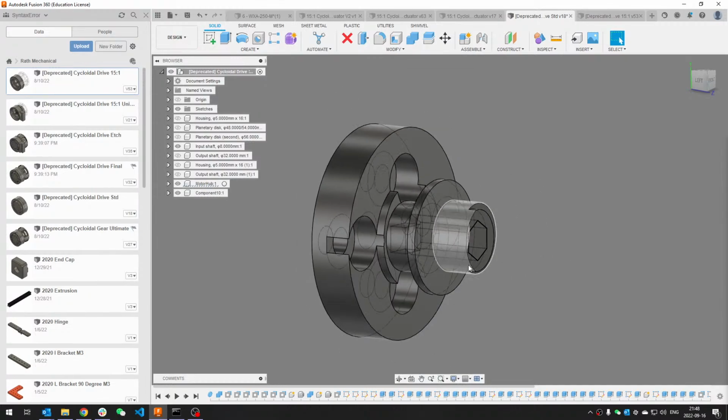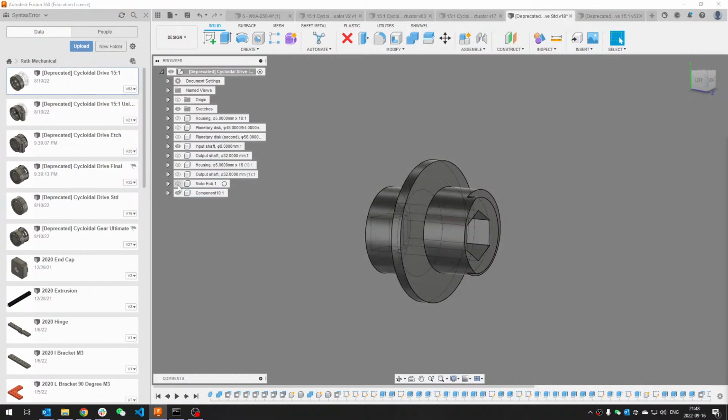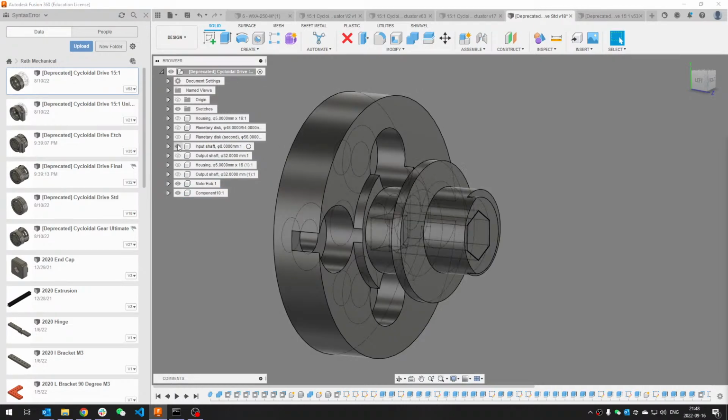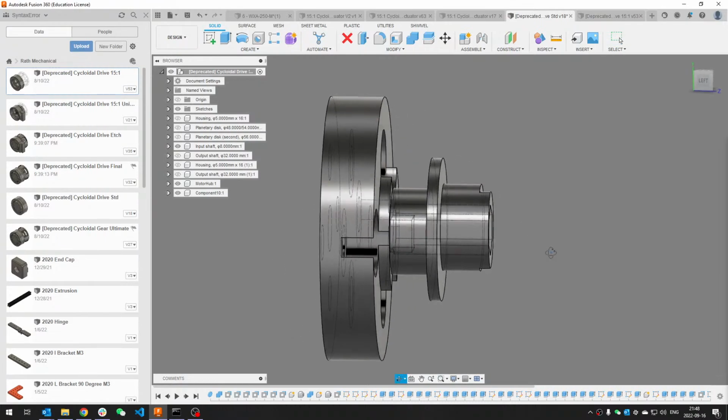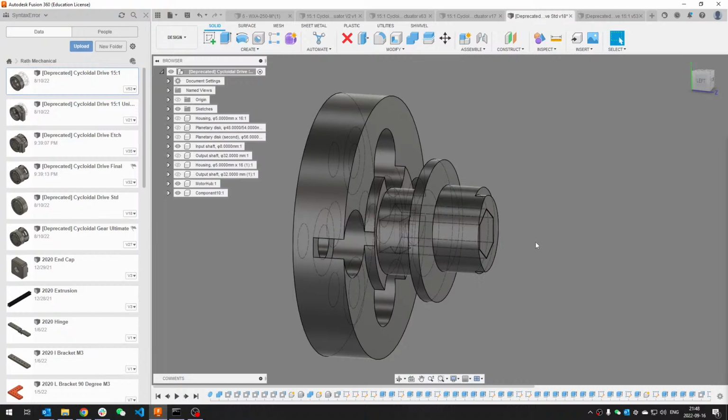Also I hesitated about how to put things together. This is one solution. I have the motor hub here and the generator here, and they need to be two parts because there is a bearing here and a larger piece here, so you cannot put the bearings through to the middle. Another way to do it is to have this part fixed to this part, and the mounting point is between these two.